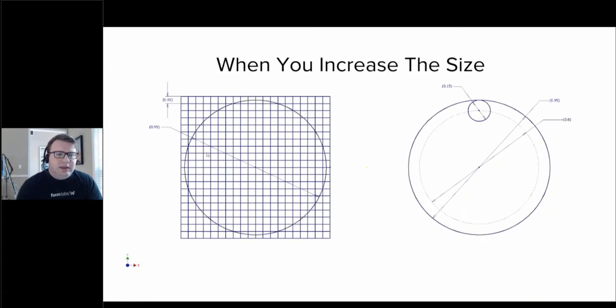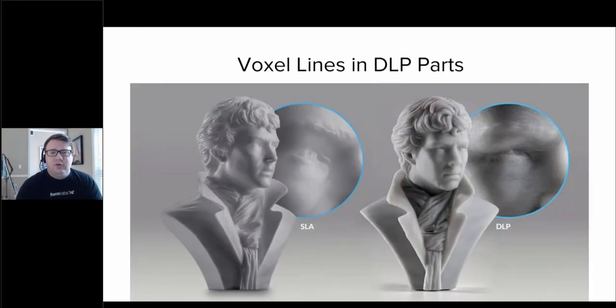But with a DLP, it can't quite do that. So laser-based SLA 3D printers really can achieve a larger range of tolerances due to the fact that they don't have to snap to these individual pixels. And this has all been a very basic example with just a simple peg. But when you scale this to some 3D geometry, you can see what really happens. With a laser-based machine, since you can make these fine steps, you can achieve really smooth surface quality.